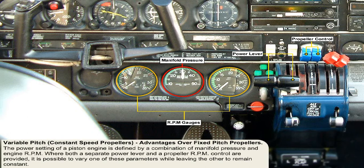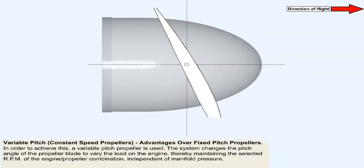Where both a separate power lever and a propeller RPM control are provided, it's possible to vary one of these parameters while leaving the other to remain constant, so optimizing the operation of the engine-propeller combination to give the best efficiency and fuel economy, while reducing the engine wear and tear to a minimum. In order to achieve this, a variable pitch propeller is used.